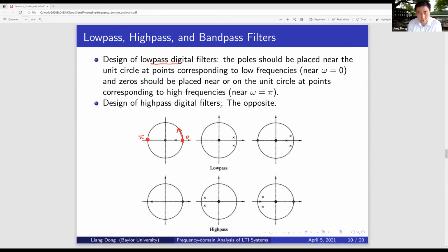So let's look at the low pass filter. I put a pole here. That's a valid pole. It is within the unit circle, giving me a stable system. And I also have just one pole, so it's a real pole. I can put two poles here. Those are valid poles because they are within the unit circle, giving me a stable system. And I want to have a real-coefficient filter. Therefore, these two poles are complex conjugate pairs. And this is the example. I have three poles. So it's all close to the ideal case at the point here.